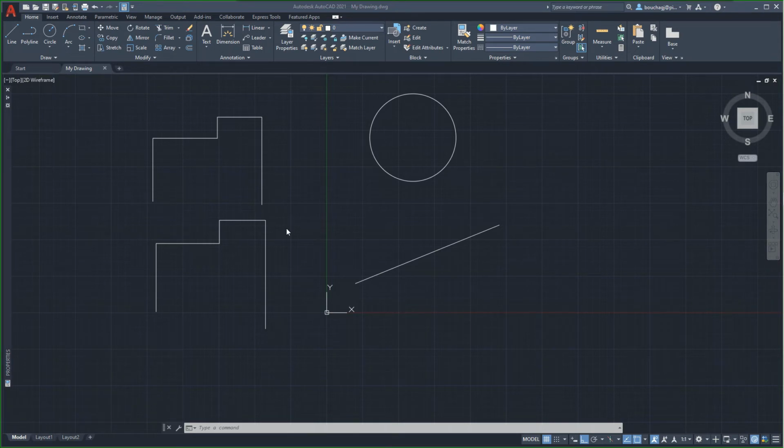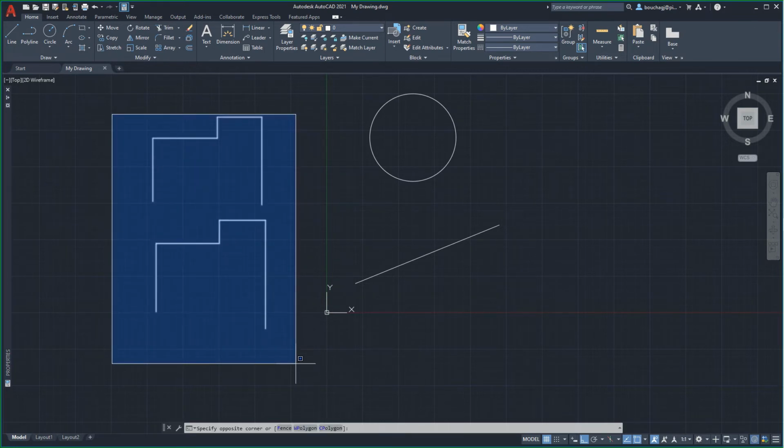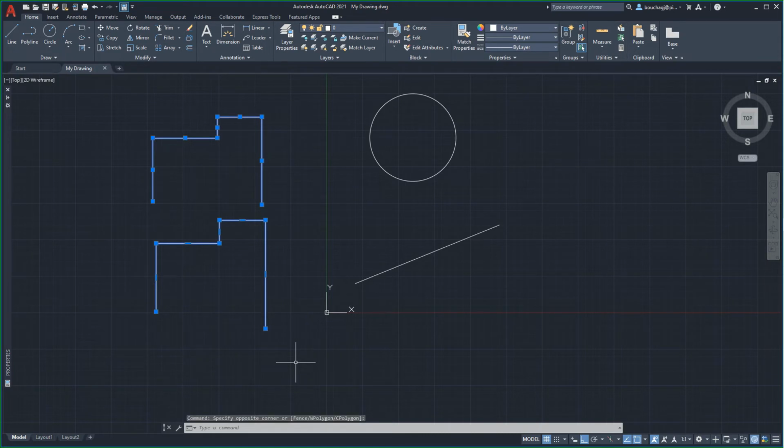There is a graphical or visual cue difference in AutoCAD that clearly tells the user if a particular line segment is a line or a polyline. Left-click in space up and left of the lines and the polyline that you have created, ensuring to fully surround the objects. And left-click again to release the selection box. Note that the midpoint of a line segment has a blue square box, and the midpoint of a polyline has a flat rectangular blue box.